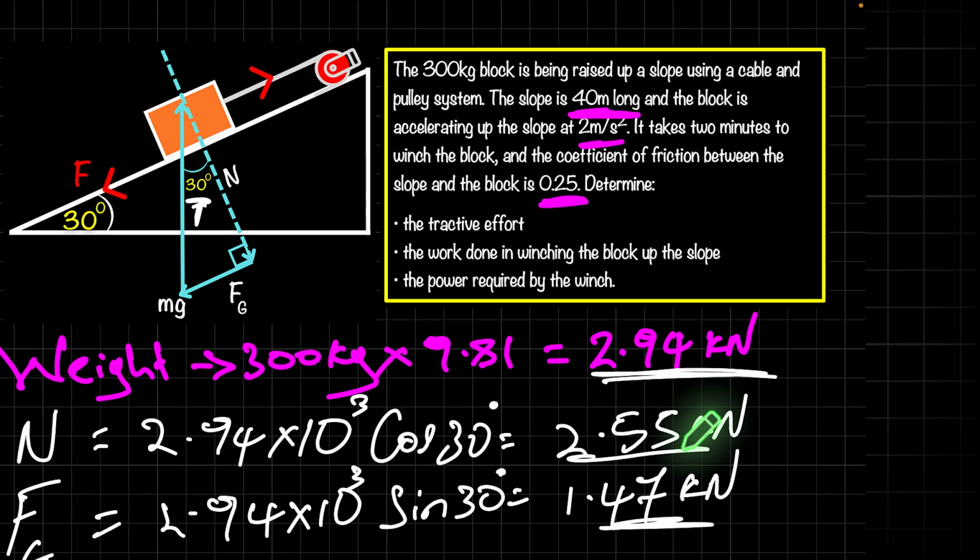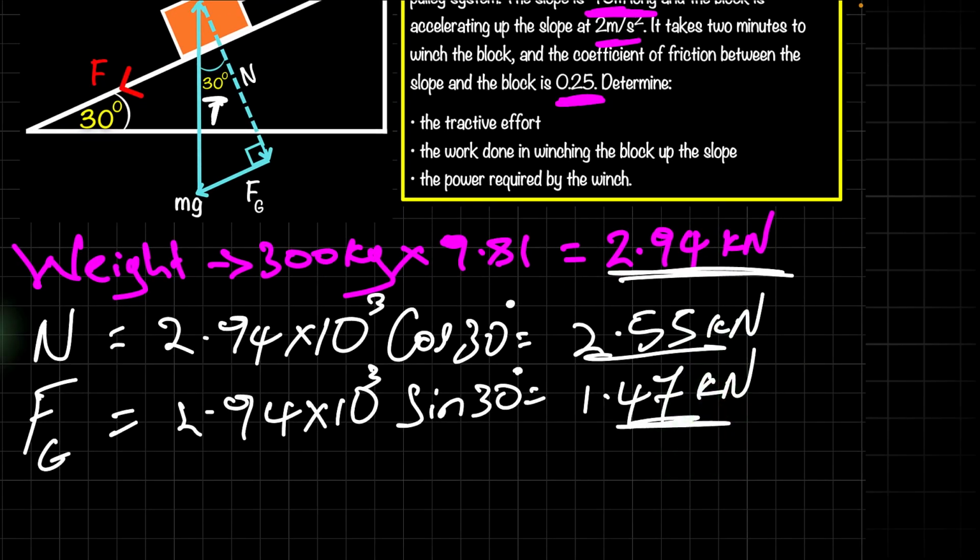So we're going to have to use that again, the friction between the mass or the block and the inclined plane or the surface. So let's do that bit now. For frictional force, I'll just use Ff. We just need to use the same formula that we had before, which is this U looking symbol that represents the coefficient of friction multiplied by our normal reaction, hence why we needed to find the normal reaction as well.